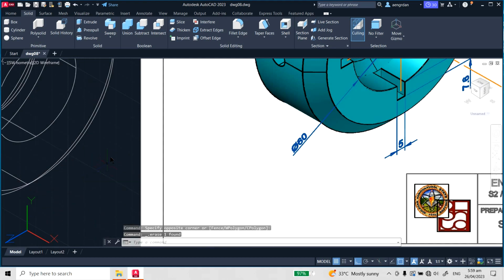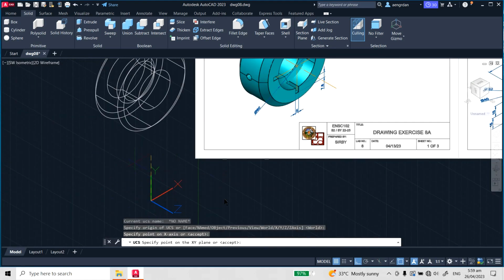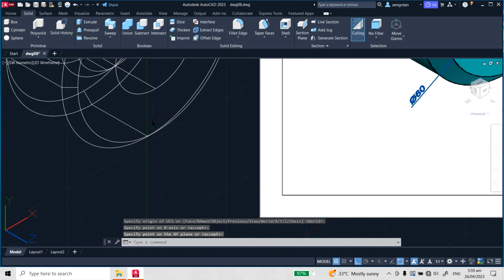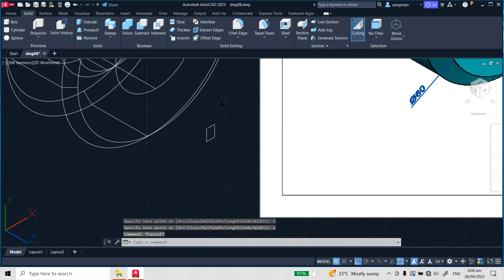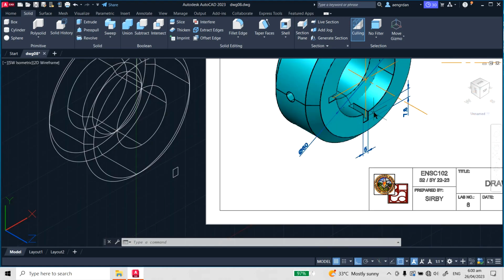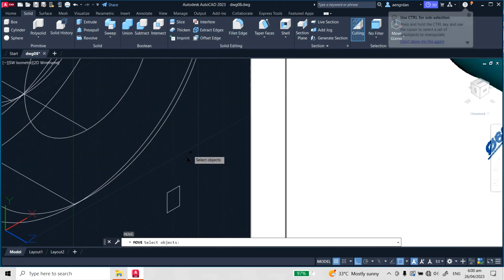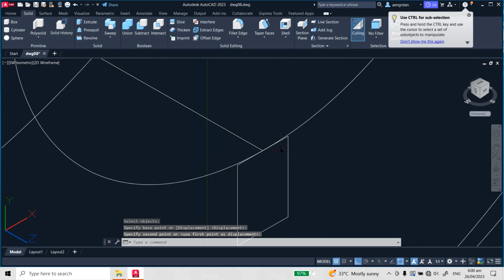Sorry, change the UCS. Okay, X along this direction and Y along this direction. So polyline, we have 7 and then 5, 7 and then close. And we notice here our distance is only up to this, or the slot distance from this face to that point only. So I'm going to move this. The midpoint must coincide with the quadrant.